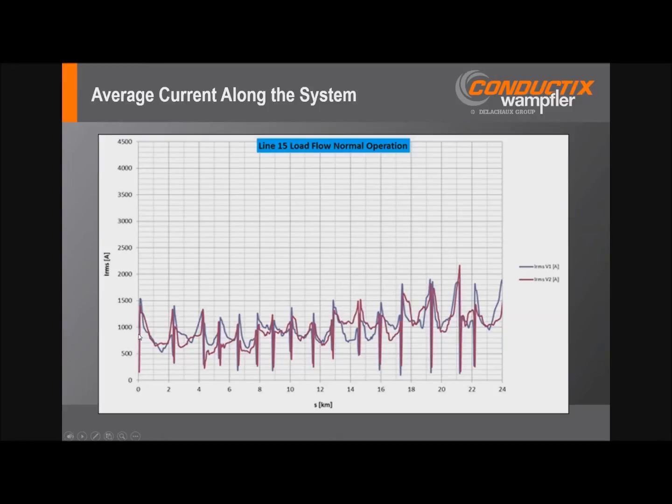So the way this is essentially designed is it shows that as this vehicle first accelerates leaving this station, the current is fairly high and the RMS current is high because this feeder is feeding this section of bar until it reaches a crossover point at isolation. And that current demand, of course, decreases from an RMS level as the vehicle passes. So the RMS current levels are highest, obviously, closest to the feeders. They drop off as you move away. So this is normal operations.